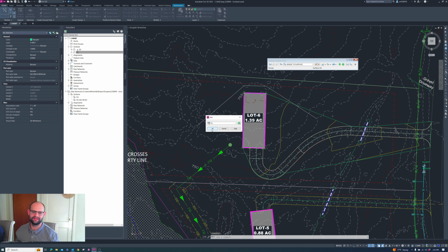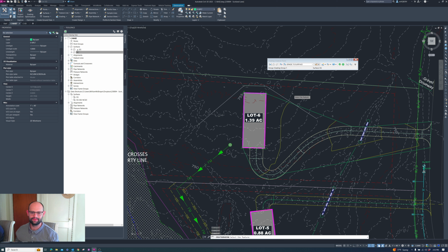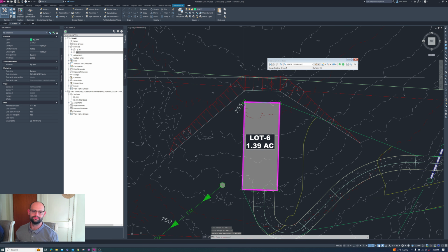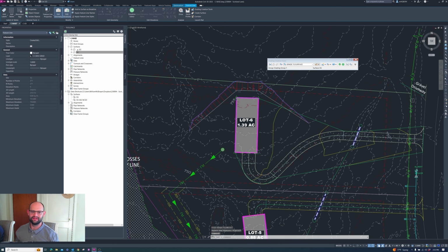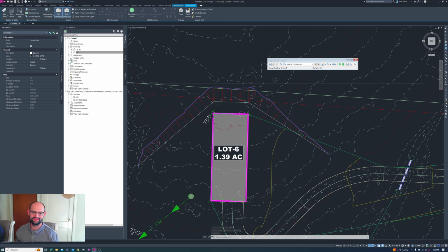Site, this is on the FG, so accept that. I will accept the default name it is created for us. OK. Now it says select the feature. This is the one we want to start with. This is the grading side that we're tying out to existing on. Click. We will apply to the entire length and accept the standard slopes. This feature line represents where we tie out to existing grade based on those criteria.